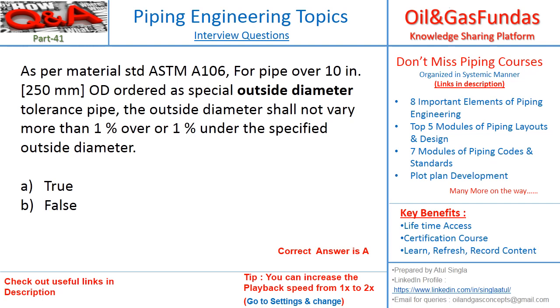The variation which is acceptable is 1% over and 1% under. Suppose you are asking for OD for a 16 inch pipe, so there may be variation in OD. The outside diameter may vary 1% over and 1% under. If it is within this range, that can be accepted by the purchaser. So these are a few of the clauses already mentioned in these standards.